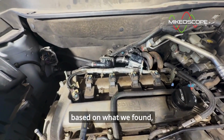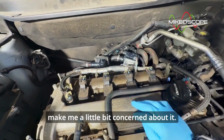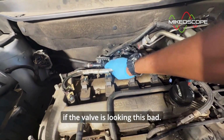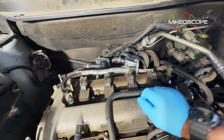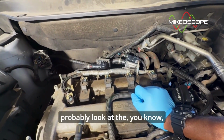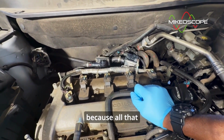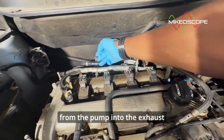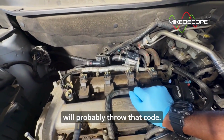All right, guys, so based on what we found, both valves are obviously working, but the deposits on this one make me a little bit concerned about it. And then it makes me wonder, if the valve is looking this bad, what do the ports in the head look like? So maybe I need to look at the ports on the head as well, because anything that clogs or prevents smooth airflow from the pump into the exhaust will probably throw that code.